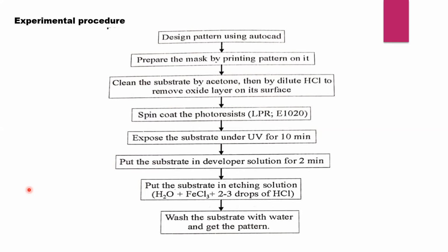So there is a need to isolate our product individually. What is the product? The desired pattern containing silicon, right? So that we got, but we got it along with the photoresist molecules. So we need to wipe out, we need to etch out those photoresist molecules, for which the next operation to be done is the etching process.